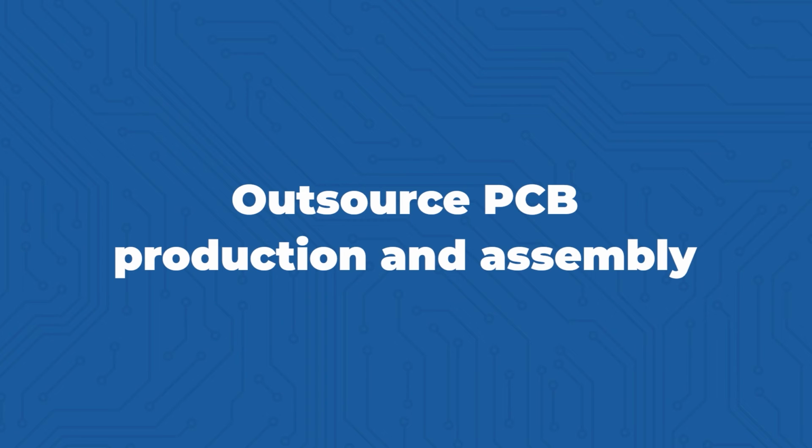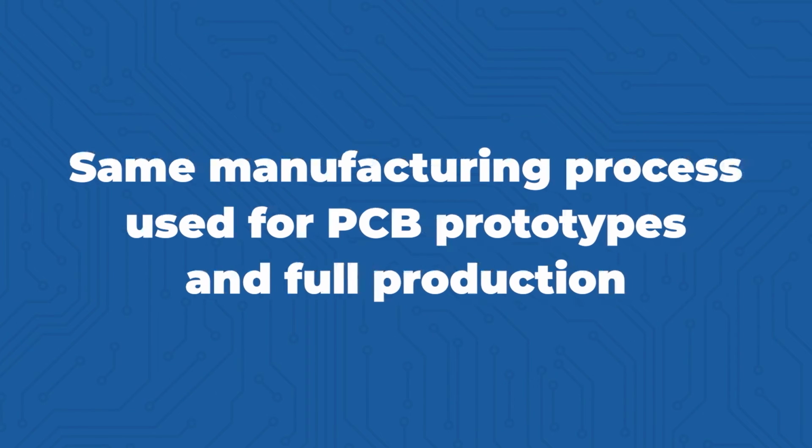It's much better, I feel, to outsource the PCB production, both the board itself and the assembly process. That eliminates any complications in debugging as far as being concerned about the quality of the board assembly itself. And secondly, eventually you're going to have the boards mass produced. The method used for producing prototypes when you purchase them from a prototype company is the same procedure used for production. You're going to have to go this route eventually, and the earlier you transition to the production process, the better off you are.